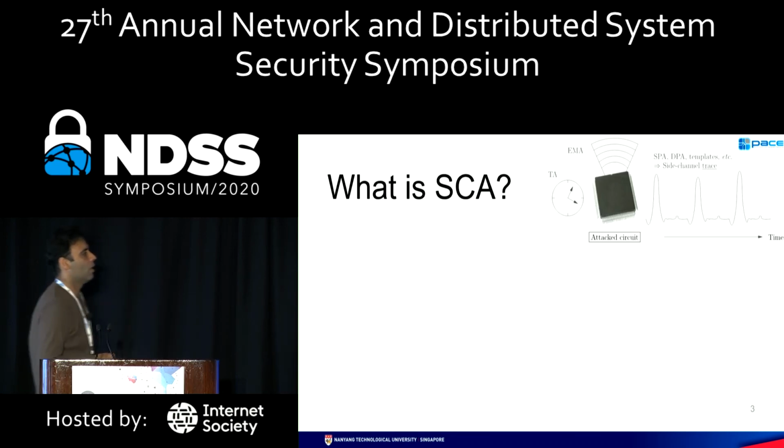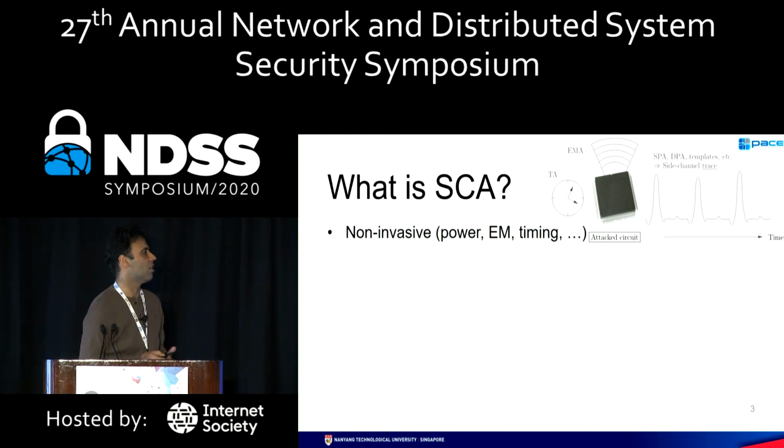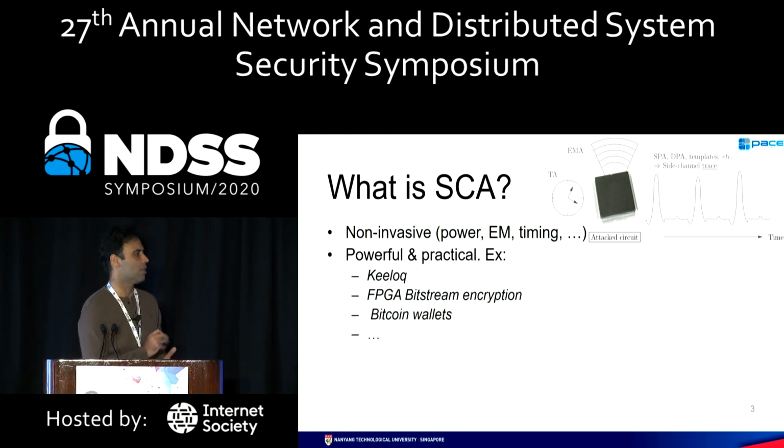So just to summarize what a side channel attack is, in very general terms, it's a non-invasive attack, which means we keep the chip still functioning. Sometimes we might remove some layers from the device, but we keep it functioning in its normal form, and then we look for the physical parameters which can leak sensitive information.